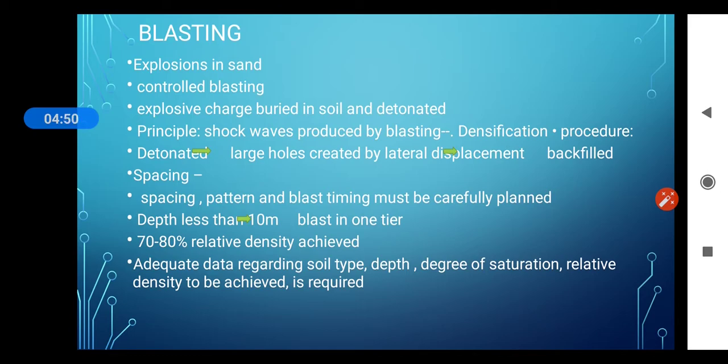The casing is withdrawn, and a wad of paper or wood is placed against the explosive charge to protect it from misfire. The hole is backfilled with sand in order to obtain the full force of the blast. The electrical circuit is closed to fire the charge. A series of holes are thus made ready.